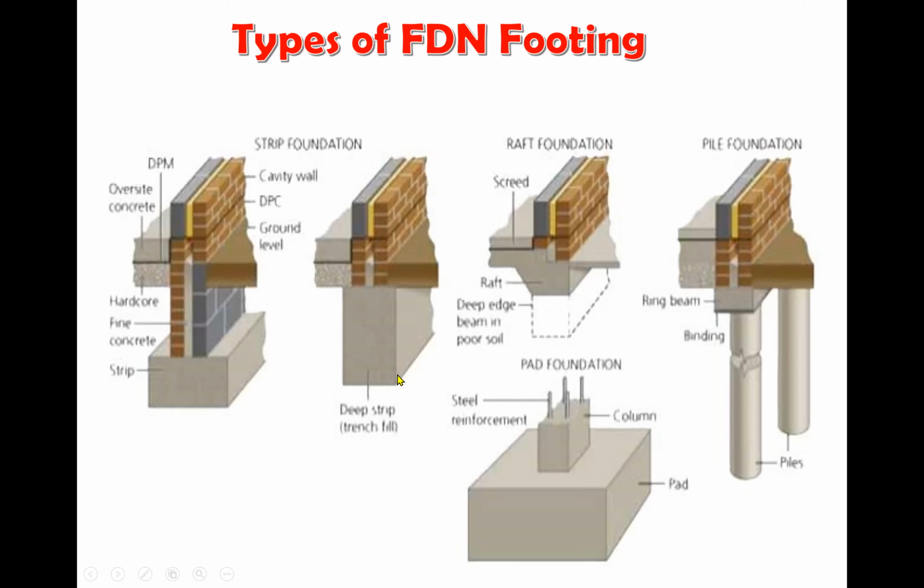I can tell you that most people out there usually resort to narrow strip and not the deep strip. That is why sometimes we have cracks in our walls, because when settlement takes place and the wall slips, that means it's moving, and it causes the walls to crack. You see the crack from the floor up to the window sill and sometimes elsewhere in the walls, and that's a problem. All right, so we use deep strip. Not going too deep, your technology class should go a little deeper than that, but just to give an idea what kind of foundation is recommended for the type of soil.